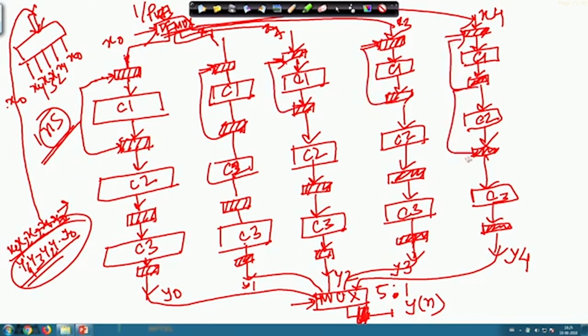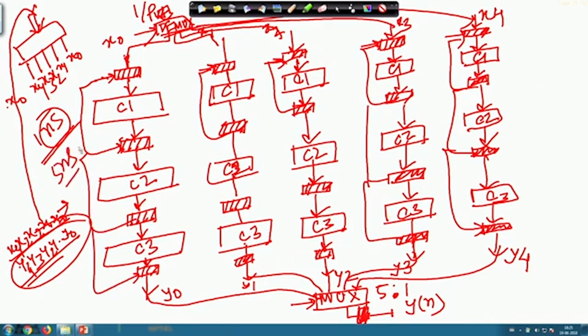And this block is connected to the same clock, and this clock will be 5 nanosecond, which is the requirement of the processing elements' critical path, the requirement for the clocks of these registers. So, the clock period for each of these registers is 5 nanosecond.